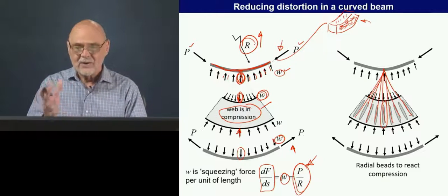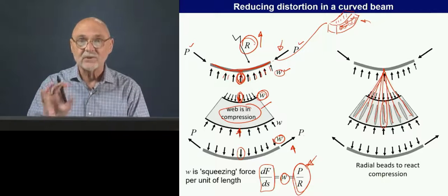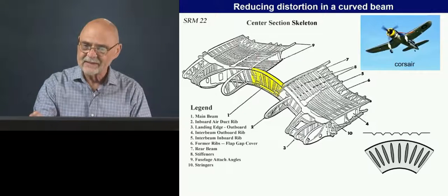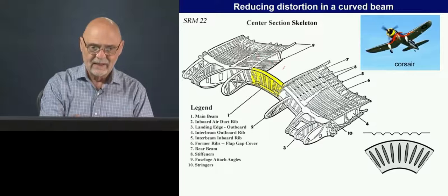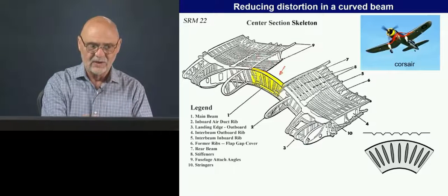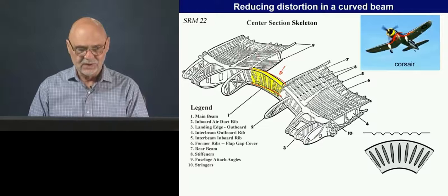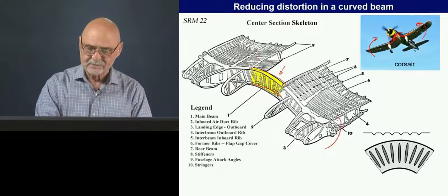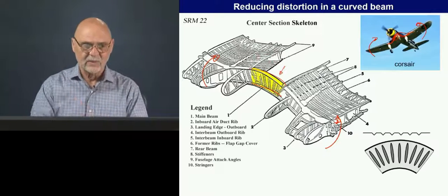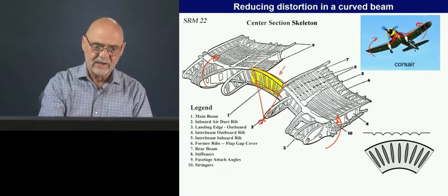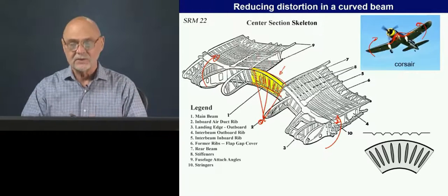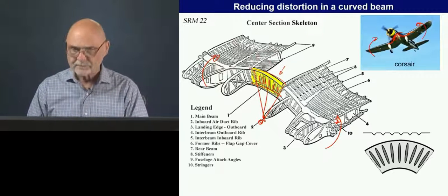Okay? And I don't have a good example for this in automotive construction, but here is one in aircraft design. So this is looking at where these wings go, kind of up above the fuselage here. And you can see this area here, thin wall structure, and you can imagine that the wings there's a big bending moment here. So it's loading it just like we looked at. Here's a radius of curvature of that area. And then here are the beads that they've added to improve that.